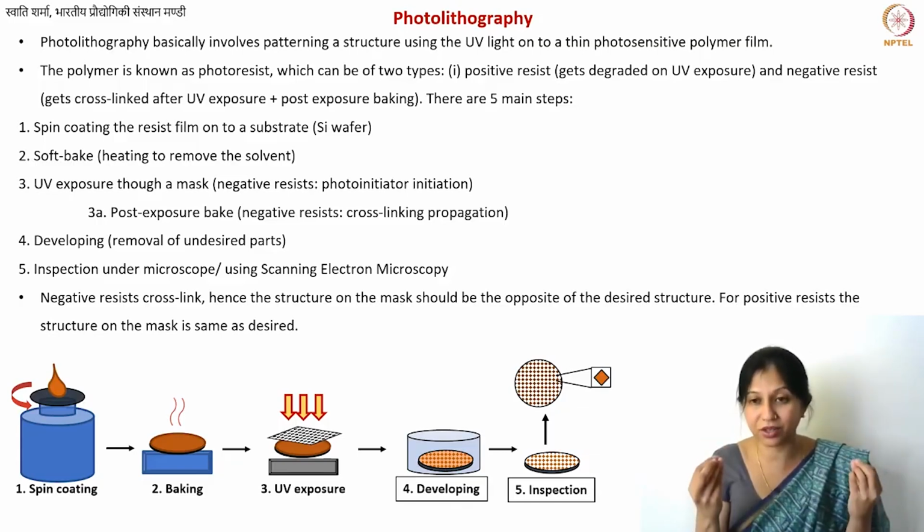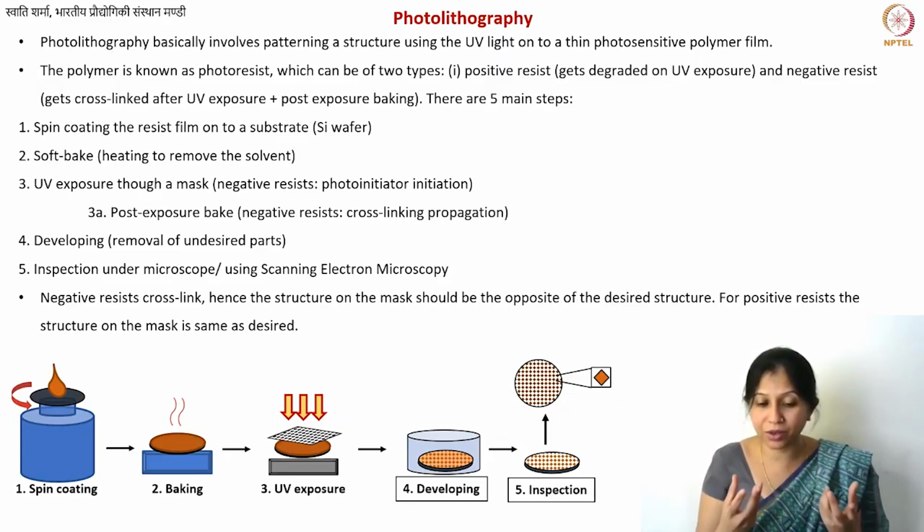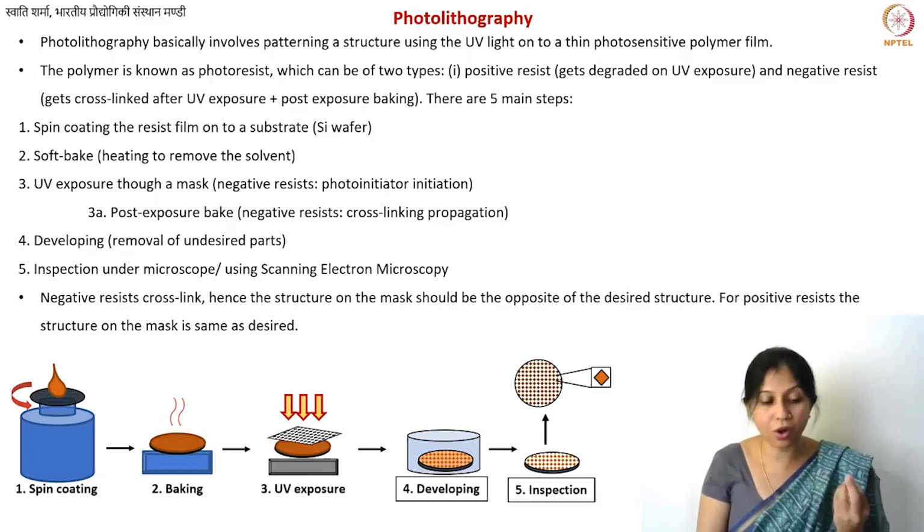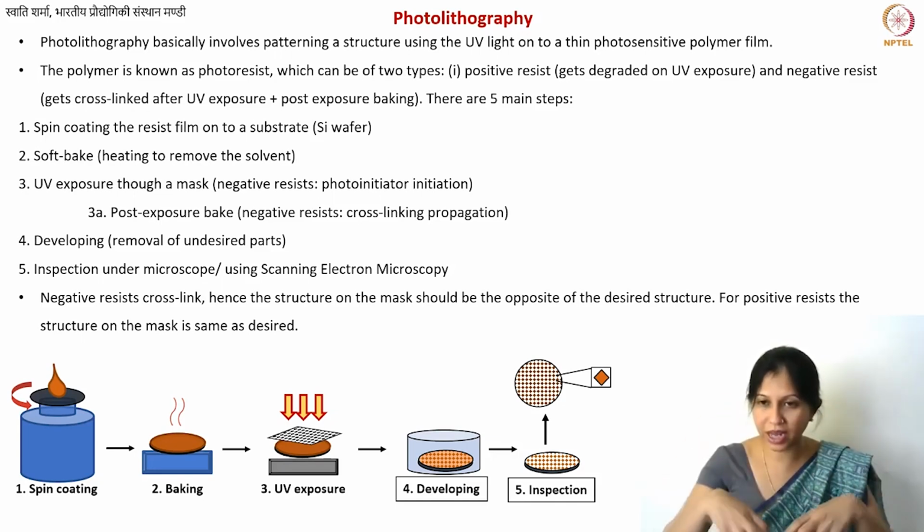These micro scale structures you cannot really see with the naked eye when they are very small, so for alignment you need microscopes, and that is why you have this overall setup. You can also perform UV exposure through the mask. You also have something known as a maskless lithography setup, where you don't have a physical printed mask, but you design it in a certain software, and then through that you expose the UV light to your structures.